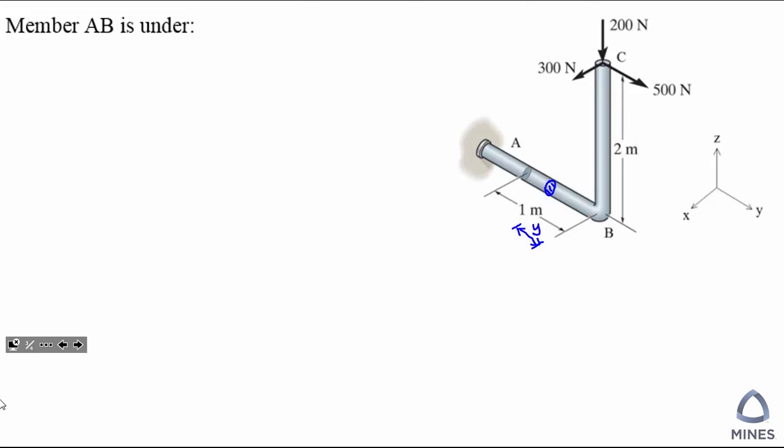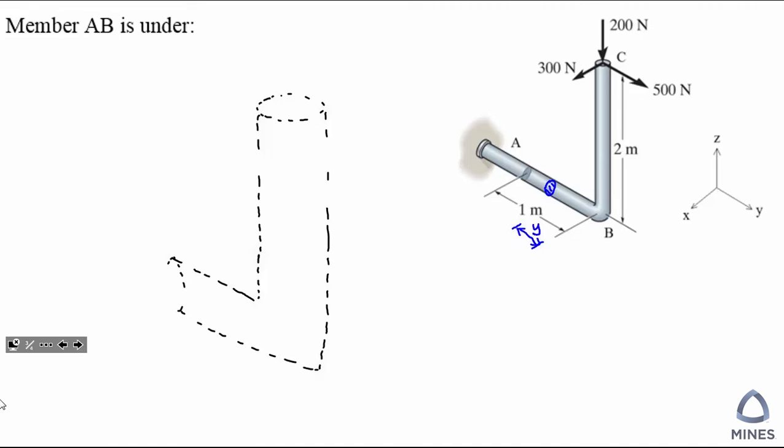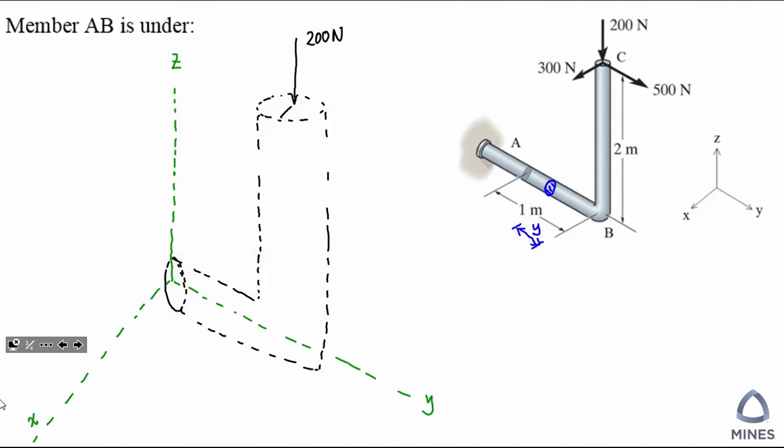No. Are we going to have the same internal force? The answer is no. So let's take a look. Again, we are going to use the free end side as our FBD. So this is your cutting plane, the free end side FBD. So the first thing you are going to do, again, try to set up the coordinate system at the cutting plane. So now the next thing is try to draw the external force.